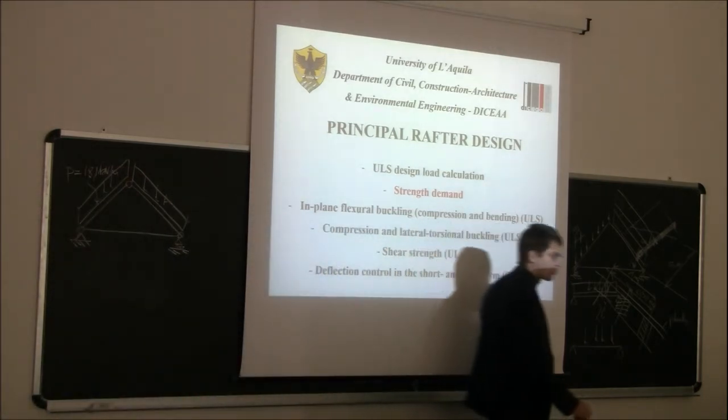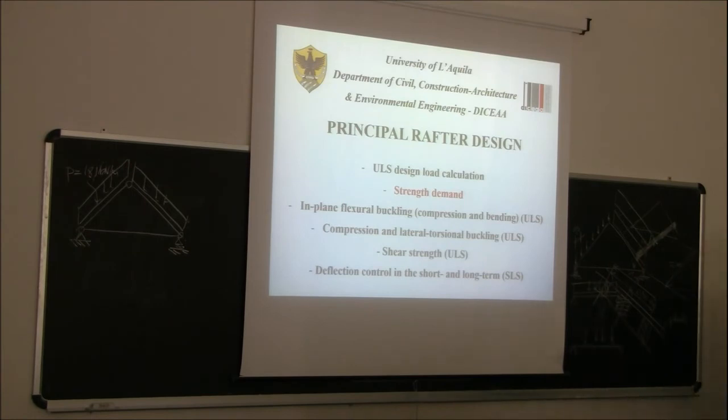So this is our structural system. We need to solve the structural system. What does it mean to solve the structural system? It means, first of all, to find out the restraint reactions, okay? And then to solve internally, to find out the internal forces: axial force, bending moment diagram, and shear force.